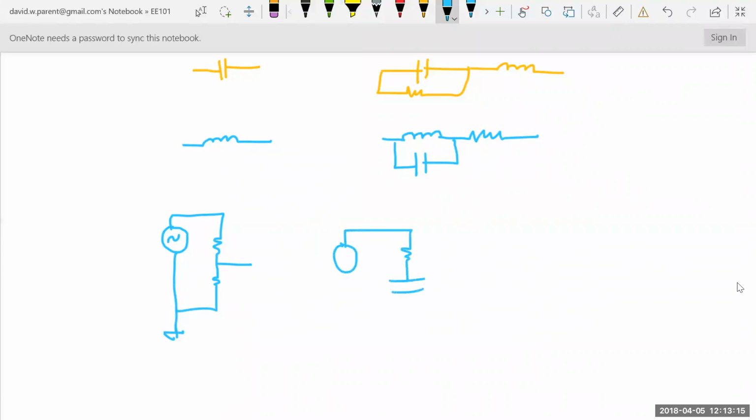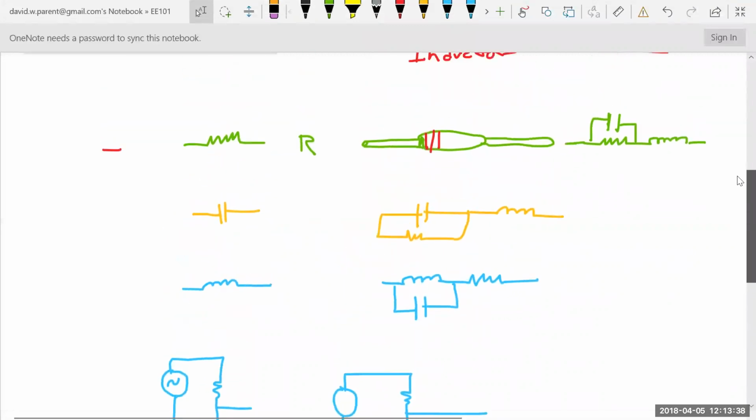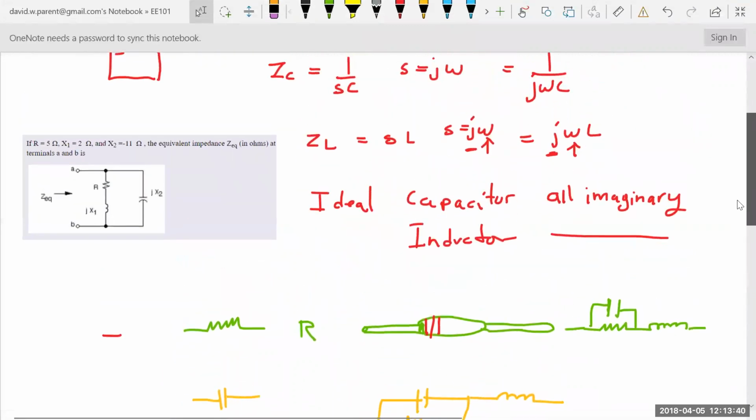And also, let's say we're doing this kind of thing, is that even though this has inductance and capacitance, and this has resistance and inductance, this resistance and this capacitance are like the dominating feature. All right. But when you get up to high frequencies, yeah, these parasitics can be important.